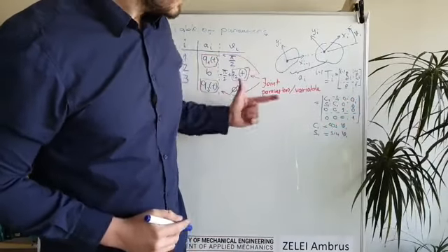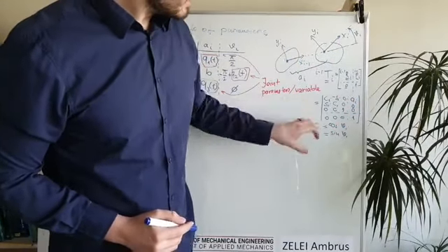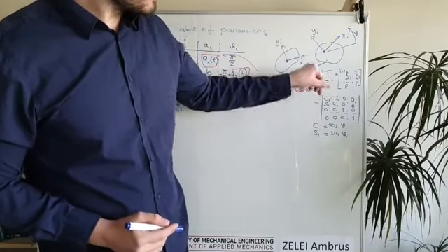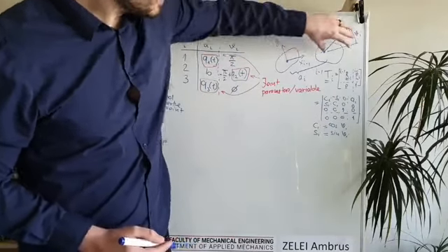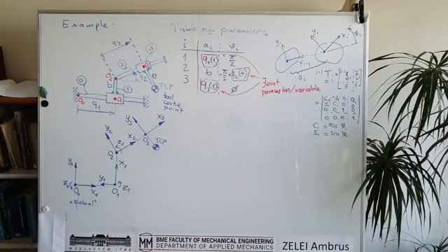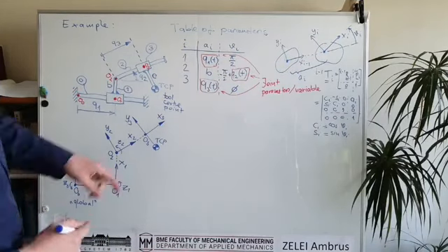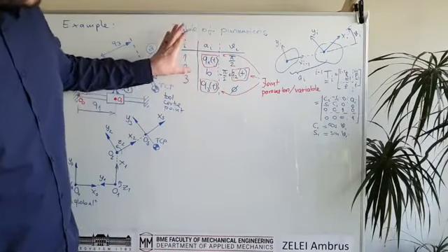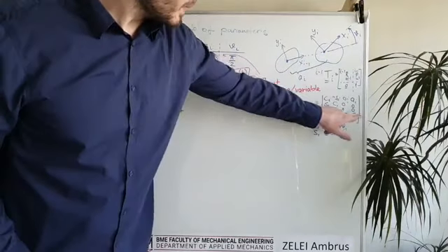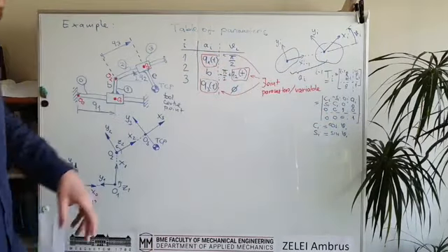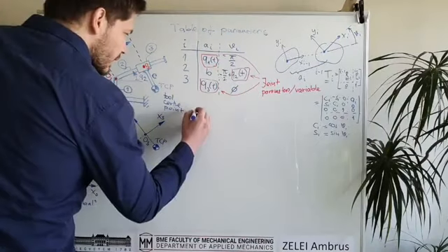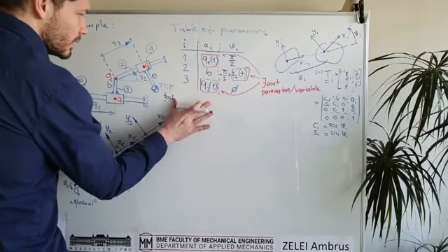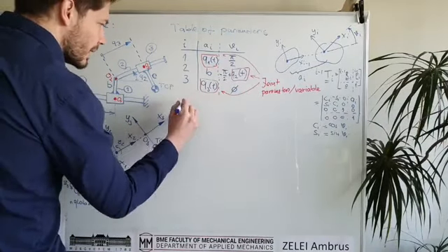So this is a translation along axis X. So this was our homogeneous transformation matrix between the two neighboring rigid bodies, and we have to basically take this table and fill up this matrix with the parameters, so we can create all of these neighboring transformation matrices.